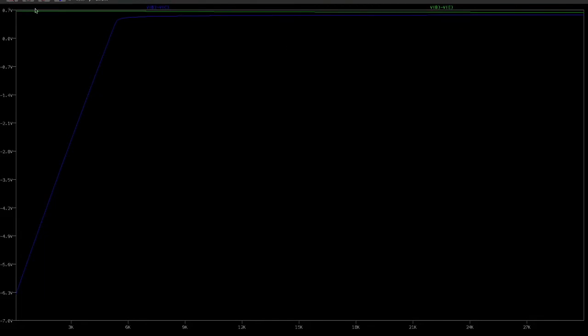Okay, so first off, it doesn't matter what the value of RC is. It doesn't affect our value for VBE. So that's always going to stick around 0.7 volts. That means our base emitter junction is always going to be forward biased, which is what we need for the active region. But we see here that our voltage VBC, which determines whether our base collector junction is reverse or forward biased, varies pretty drastically with changes in RC.